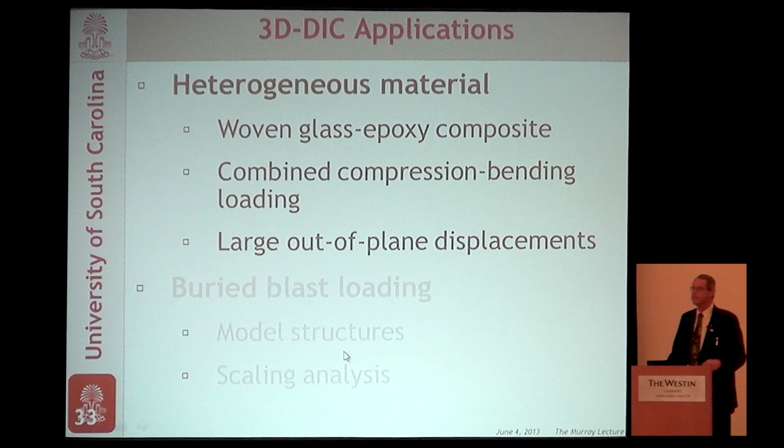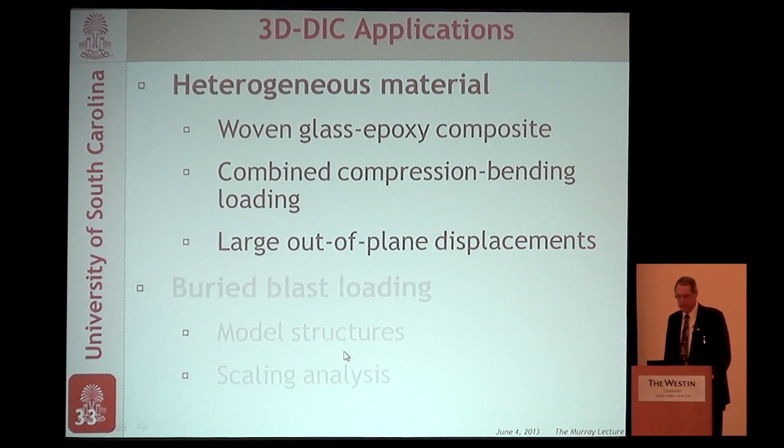Okay, so that's the kind of things that's been done for it. I want to talk a little bit more in detail about two applications. The reason I'm going to show these is because they show the power of the techniques. In this case, it's going to be 3D DIC that we're going to talk about. I'm going to talk about a woven epoxy composite under combined compression bending.